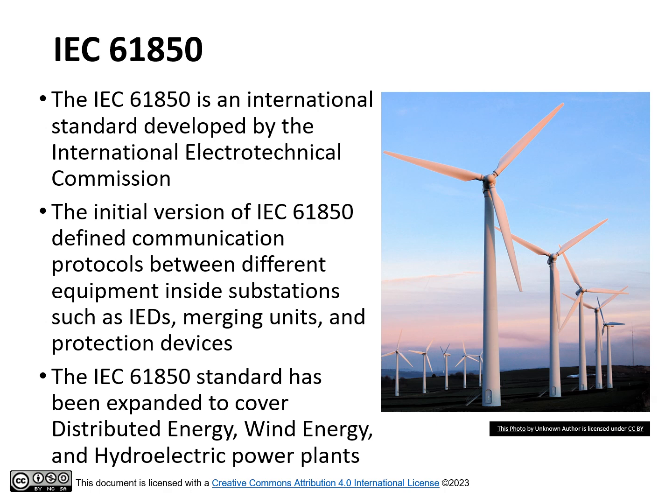The IEC 61850 is an international standard developed by the International Electrotechnical Commission's IEC Technical Committee 57. The initial version of IEC 61850 defined communication protocols between different equipment inside substations, such as IEDs, merging units, and protection devices. Based on the success of the IEC 61850, the standard has been expanded to cover distributed energy, wind energy, and hydroelectric power plants.